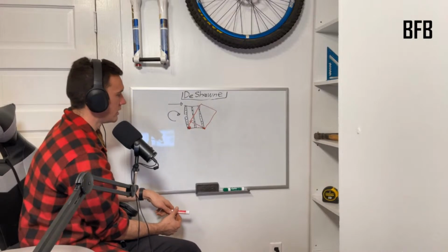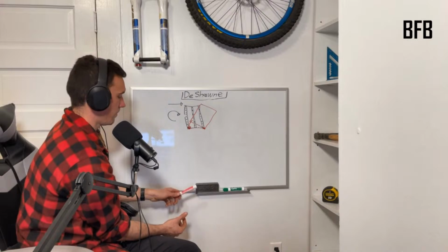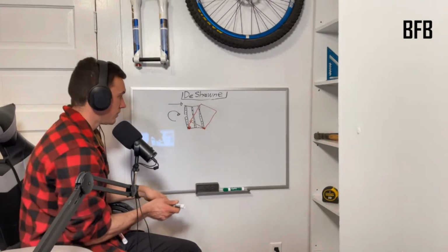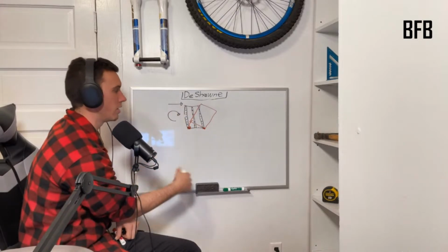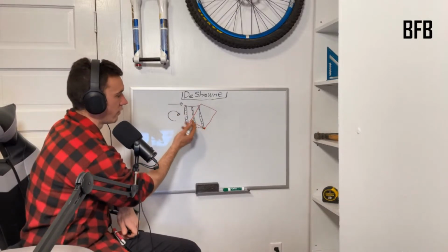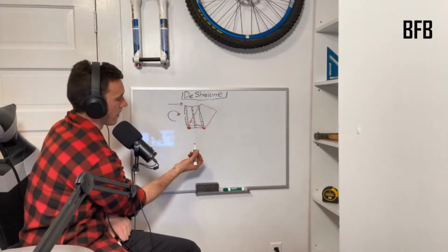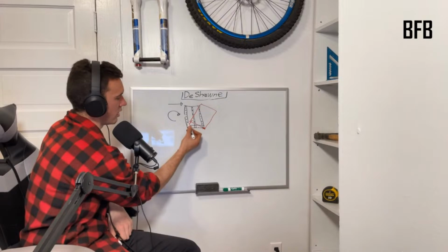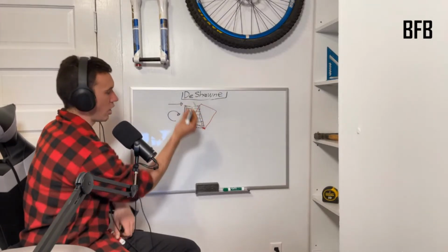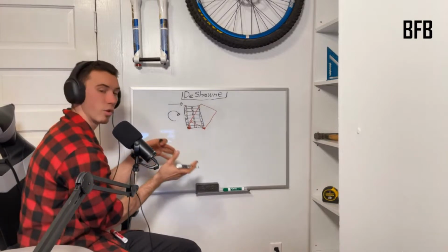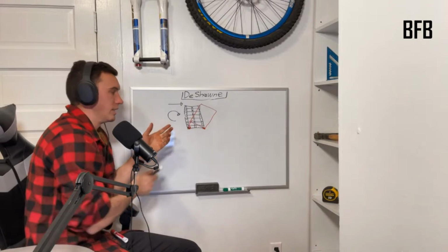So how is it that the plank products work? Well, all the plank products are doing is they're doing the exact same thing as this. They're just small scale and repetitive. So what if we took the same sheet product and we cut a little strip off the bottom? And then we decided one strip's not good enough. We're going to go ahead and cut it into strips like this. And then we're going to install each strip in the same place that the whole sheathing panel was. And the question is, is that just as strong?